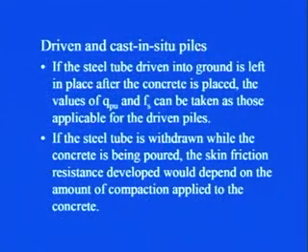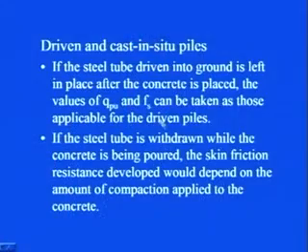If the steel tube driven into the ground is left in place after the concrete is placed, the value of QPU and Fs can be taken as those applicable for the driven piles. That means in case of cased piles, you remember that I told you this is what applies in case of driven and cast in situ piles. So, if the steel tube that has been driven into the ground has been left in its place, then whatever is the value for driven piles that you got in the first case, you can use simply and confidently in case of driven and cast in situ piles.